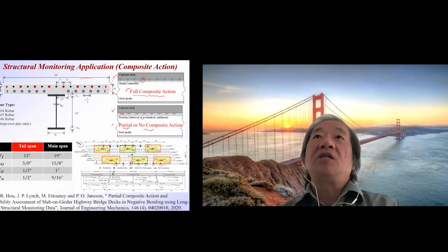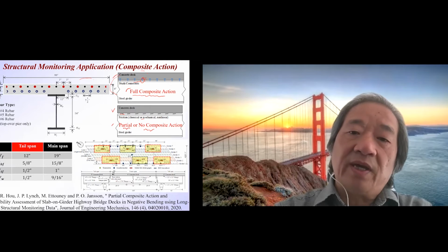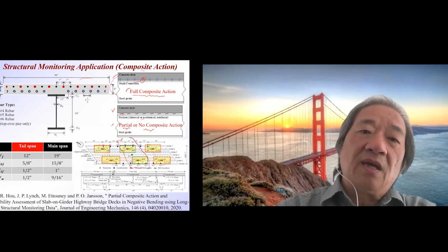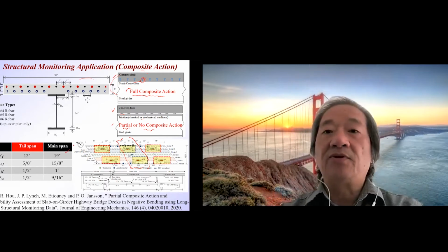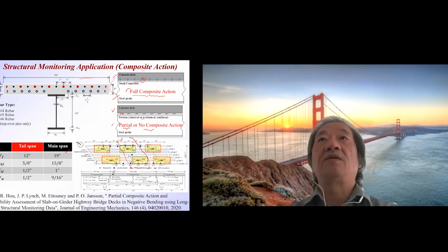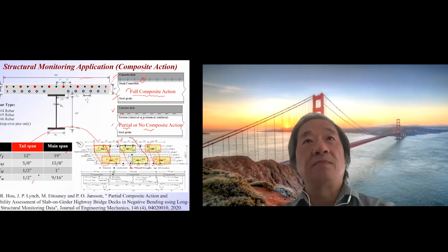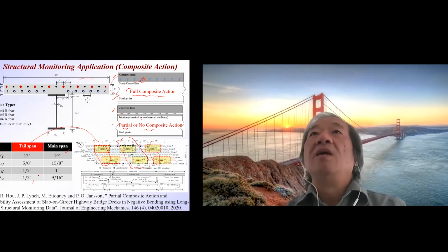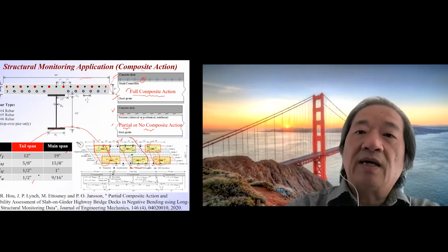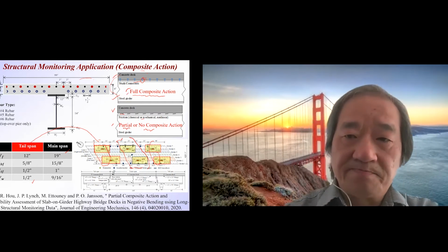So in this particular overpass, the Telegraph bridge, in the main span we have a much heavier girder, and we can foresee that it has full composite action. And then the tail span is the 2N, okay? That is a lighter girder. It makes sense, a lighter girder, because they're closer to the pier support. But then they tend to ignore the full composite action when they design and put things together.